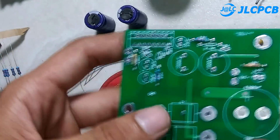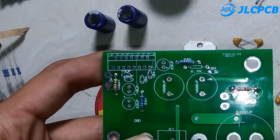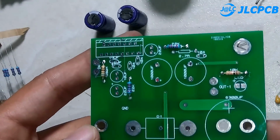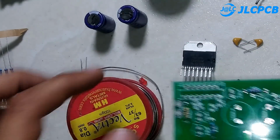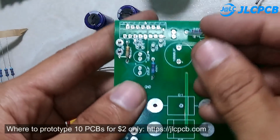So we are done with the resistors. Here it is a 2.7 ohm resistor. It's not necessary. If you are not going to solder it, then it's okay. You can leave it just like that. So I'll now take these 104 capacitors and solder them.